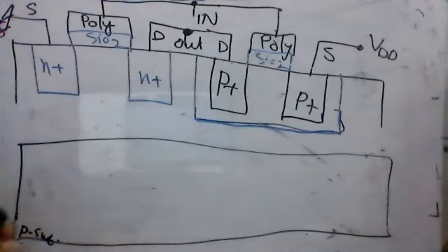Top view, it will look like this: first the whole thing will be there, rectangular, like a piece of silicon, and inside the piece of silicon, let's say there is the N-well. Let me show again, drawing it small, this inside the N-well. This was P. So first is a P substrate, this is a P type, P sub, and then inside the P sub, what was there next? The N-well. If you look from the top, you will see a big hole from here to here.